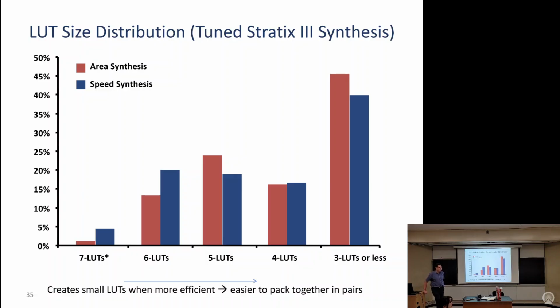Yeah. I guess for the 7-LUT case and then the 2 6-LUT case with the previous slide, you mentioned that they're kind of used for both crossbar and multiplexers. But I'm assuming the FPGA has enough multiplexers and enough crossbars that you don't really have to rely on LUTs to do that. Well, you can't get at those crossbars and multiplexers as an end user though. Like the routing is built out of crossbars and multiplexers, but the thing is you can't control it. There's no select signal, right?